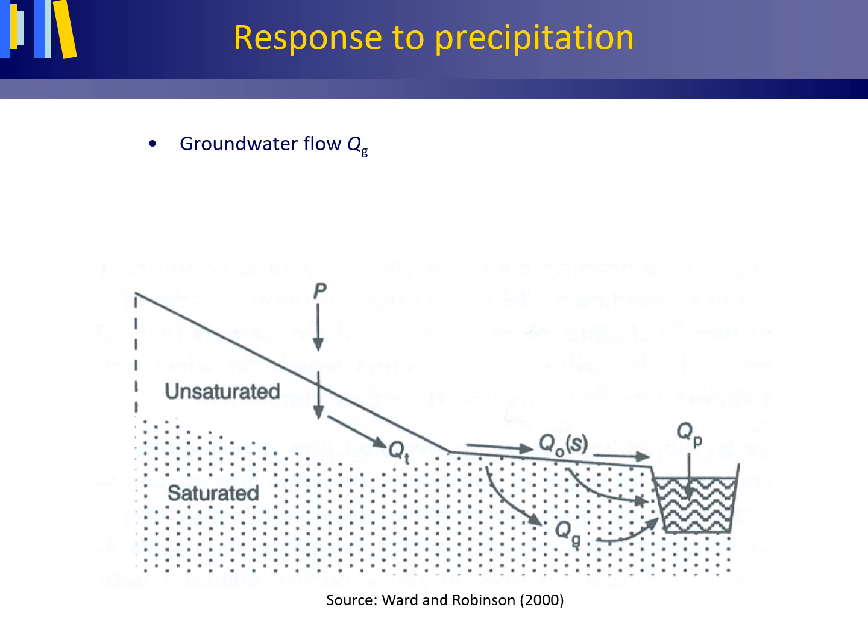When a coarse textured layer with a high hydraulic conductivity overlies a fine textured layer with lower hydraulic conductivity, the percolation capacity, which is the maximum rate at which water can percolate through a soil, is initially controlled by the coarse textured layer.